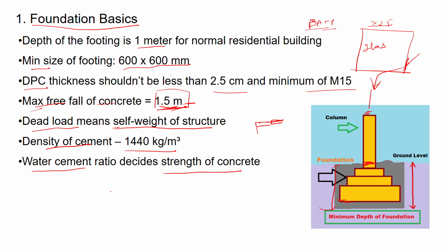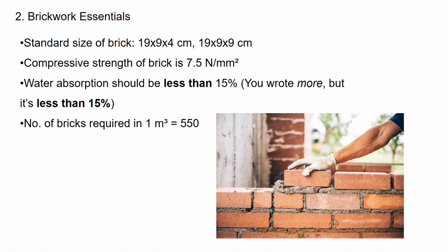Next, the water cement ratio decides the strength of the concrete. Yes, that is true, because the water cement ratio is a very important ratio when it comes to strength. For M20, M15 and everything, they have mentioned in IS 456 what water cement ratio we should provide, so please look at it.